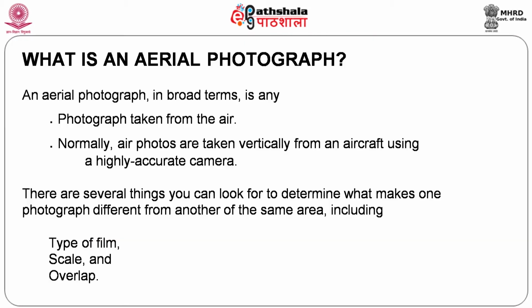As far as photographing is concerned, aerial cameras are fitted into aeroplanes and these cameras expose at different stations, take a photograph and then send it, or you can also collect the data at a later stage. These are normally taken maintaining verticality. So, very important is that all aerial photographs should have verticality, in the sense the line of sight should be vertical. If you are going to use any kind of aeroplanes, obviously aeroplanes are not static objects, isn't it? They are dynamic in nature. They will always be on the move.